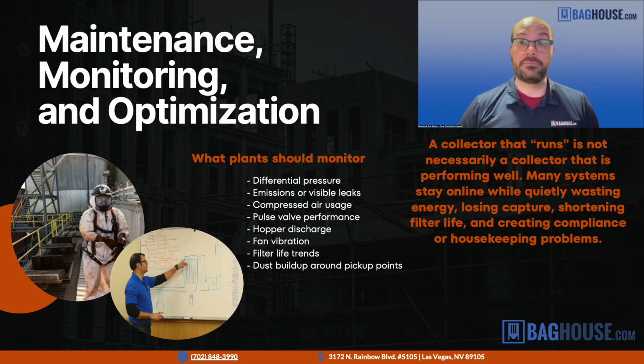If we don't have that reading, we can't rely on it and trust it. It affects everything we do with regards to maintenance, operation, planning. So we absolutely have to make sure that that system is functioning correctly. This might mean cleaning out the gauges, cleaning out the lines, either weekly or bi-weekly, or installing a device that automatically purges the lines and keeps them clear and clean. But if we don't have that information, we can't make any intelligent decisions about maintenance and operation. So we have to monitor it many times as well.